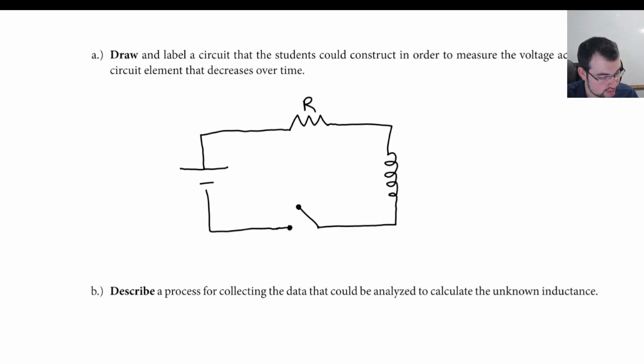What about the resistor? Well, if I pick the resistor, I'd be tracking the potential difference across the resistor. So as soon as I plug it in, there's no potential difference because there's no current. But the current is going to build and build and build and build. So actually, the resistor is not the right answer because the current through the resistor builds up like the exponential approach graph. So the voltage will also build because of Ohm's law. So by elimination, that leaves us with the inductor. So why is the inductor the right choice?